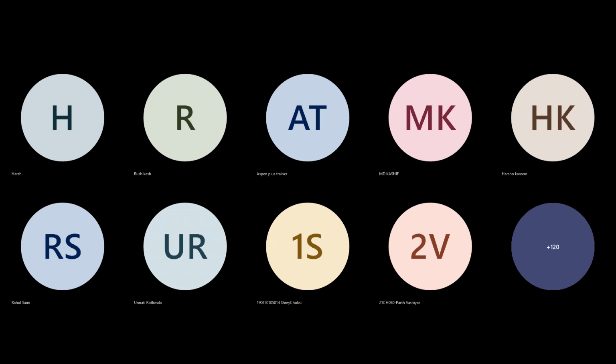Okay. Sir, in case of manual valves, which valve can we prefer, sir? In case of manual valves, which type of valve can we prefer? Mostly for a recirculation line and for a lesser flow service, plug valve is the ideal choice. Plug valve or ball valve generally we use. Most of the time with chemical industries we use plug valve or ball valve, and similarly for refineries the gate valve and the globe valve are the standard choices. Okay, sir. At lower flow rate, plug valve and ball valve, and at higher flow rates it is gate valve and ball valve.